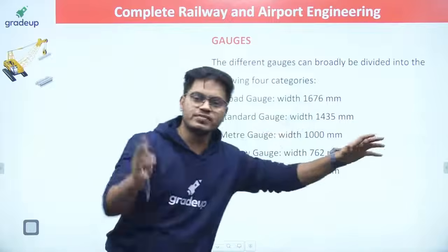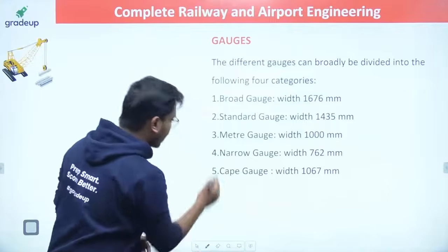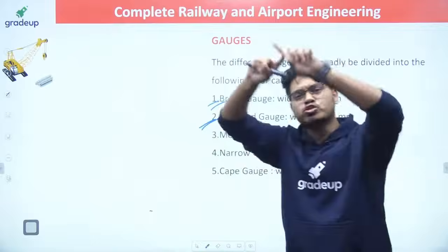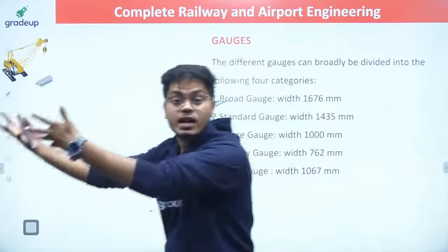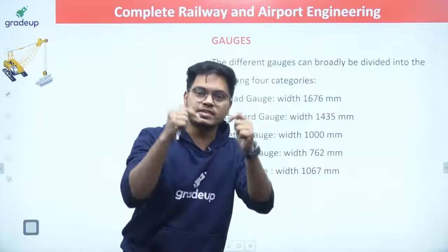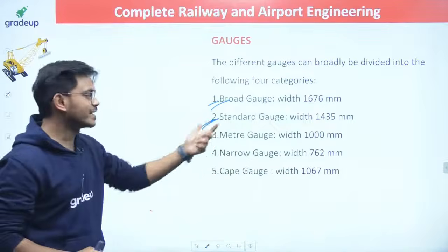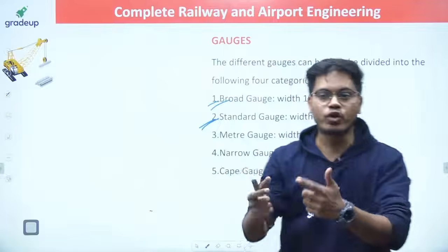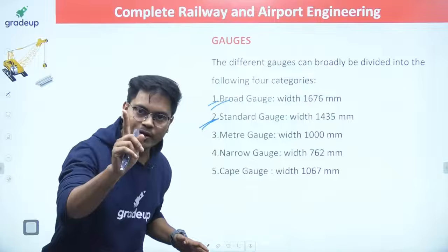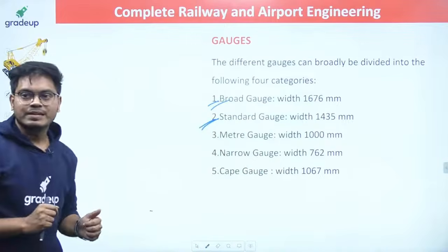This is the uni gauge policy which India is following. Okay, guys, why are we using standard gauge again in the metro and why not broad gauge? Because most of the places in other countries, people are using standard gauge. Now it is easier to get the components, or you can say the coaches of the train, for a standard gauge, as the demand is high for standard gauge coaches and bogies of the metro. All right, so availability is easy. That is the reason.